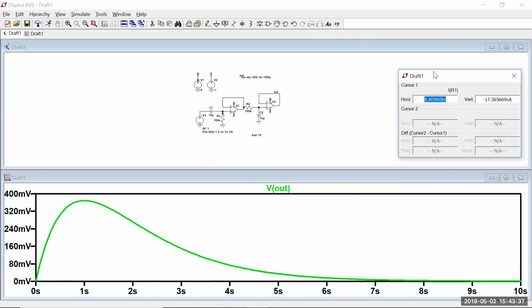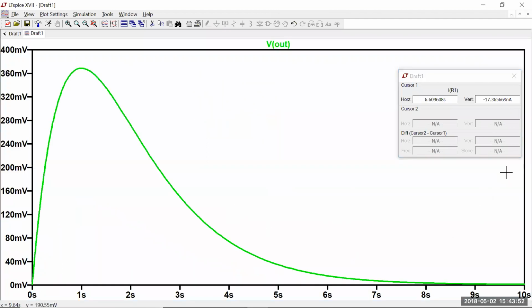Because a bandpass, right, it's blocking frequencies in the middle, right? So that means it's trying to block DC, and you can see that over here, right? Because it's going back to 0, right? It blocks high frequencies because notice it doesn't instantaneously change up and then you have an exponential decay, right?